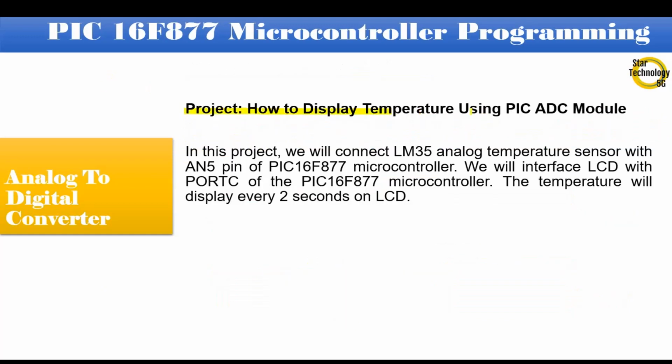Project: how to display temperature using PIC ADC module. In this project, we will connect an LM35 analog temperature sensor with the RA5 pin of the PIC16F877 microcontroller. We will interface an LCD with port C of the PIC16F877 microcontroller. The temperature will display every 2 seconds on the LCD.